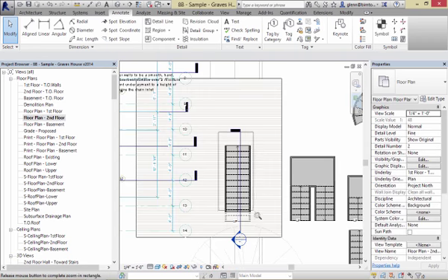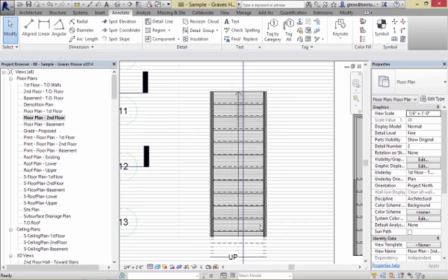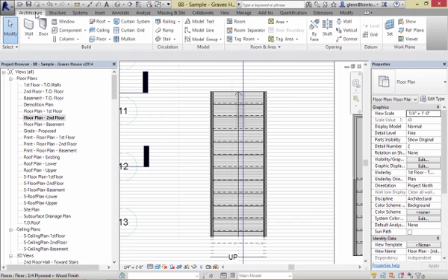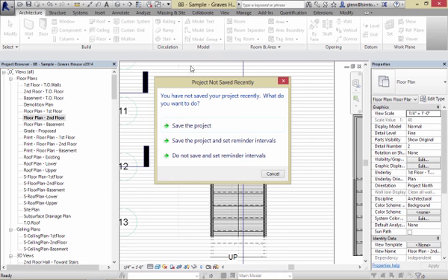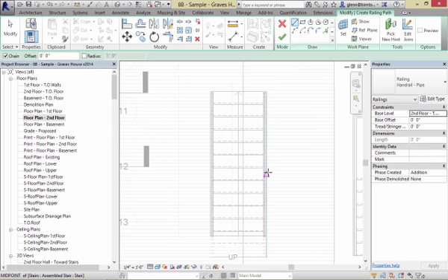We'll just zoom on in there. And we're going to find the railing tool. It's actually right next to the stair tool, right up there. Railing. Choose that. Railings have types, the same way stairs do. In fact, the railings around the stairs also have the same types. So we'll be able to find some other types. We'll just use that simple handrail for right now.